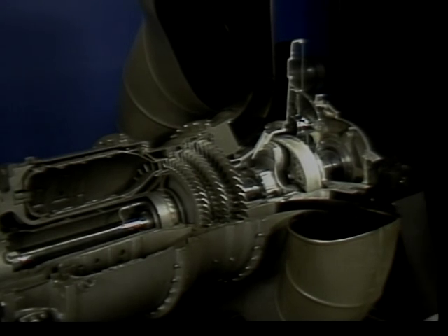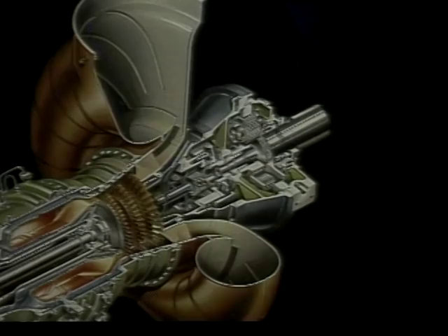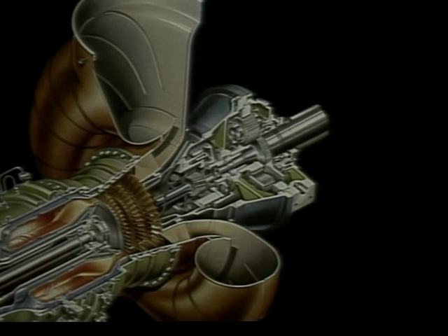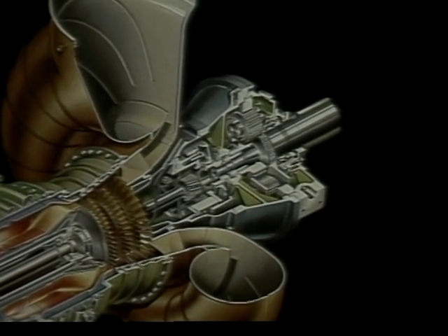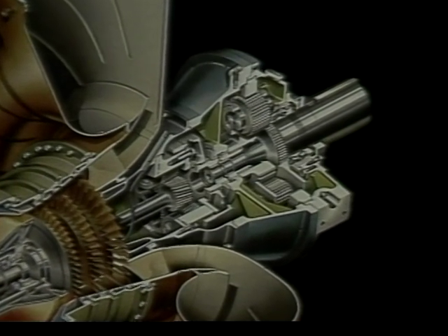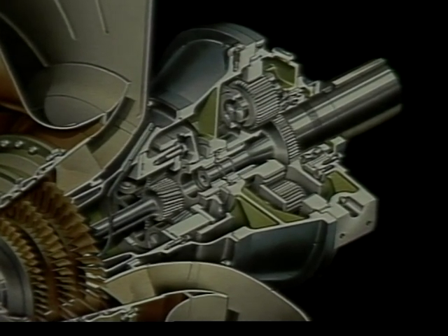The exhaust collector and turbine case are insulated with stainless steel blankets. The final main subassembly is the output reduction drive assembly, which reduces shaft rotational speed in stages from 22,300 RPM to either 1,800 or 1,500 RPM, depending on the generator frequency.